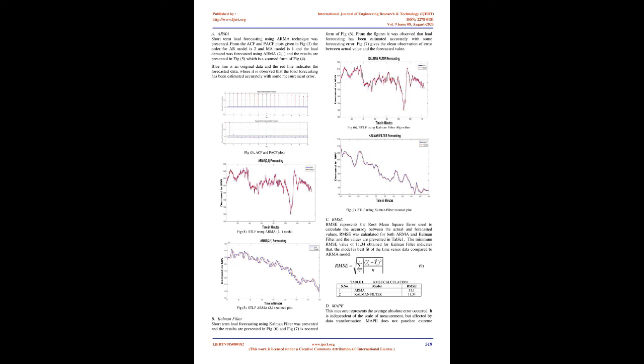P_t equals the posteriori error covariance, Q equals process noise, R equals measurement noise. To enhance the convergence characteristics of the Kalman filter, there must be a smart choice of the priori estimate state Y0 and its error covariance P0. Assumptions made for convergence of the Kalman filter applying the constant velocity model for predict and correct equations are: